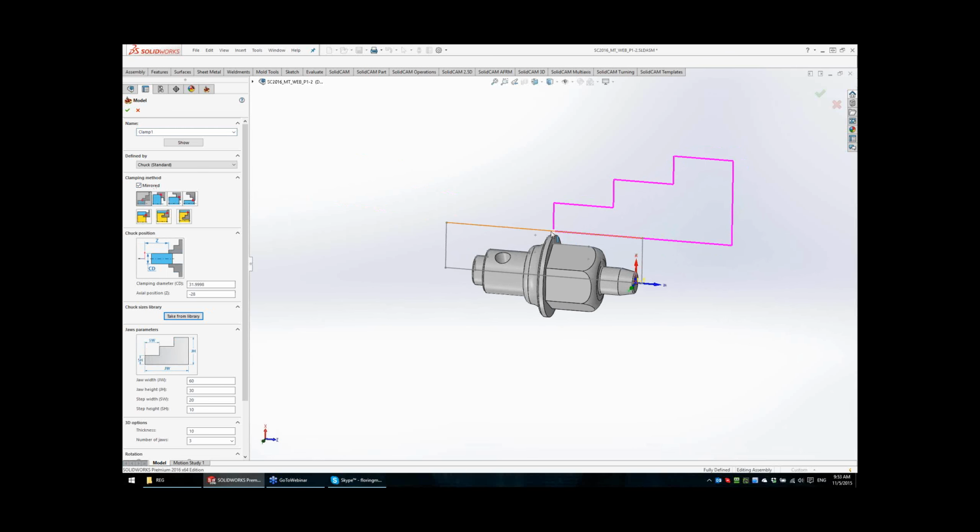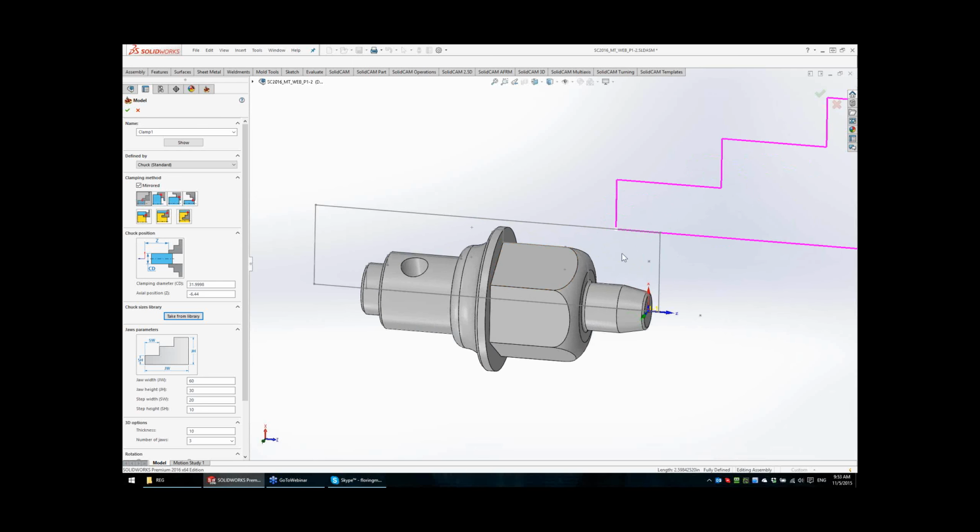For the back spindle the position is not important, because the position where I will catch the part is controlled by the MCO. With the MCO, I will command the W axis, the back spindle axis, to come and catch the part. So it's not important where I position it now, the axial position in Z. I can catch it here or here, it is not so important.